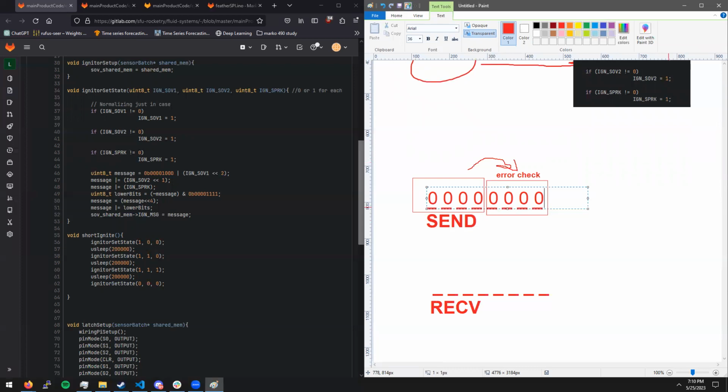Or I guess this one doesn't matter as much because it would just shut off. But in the case of all 1s, this might be because we accidentally shorted the line high, and we don't want to set off our gas, oxygen, and spark igniter all at the same time. So we wanted to avoid this.